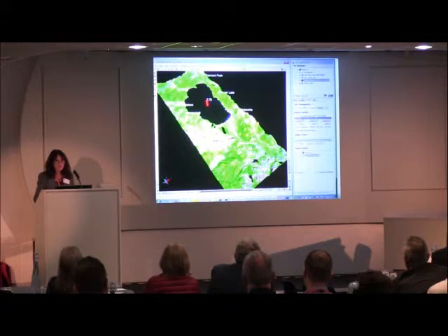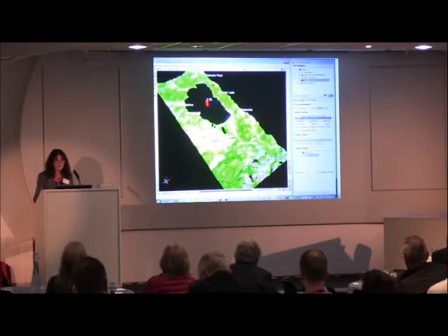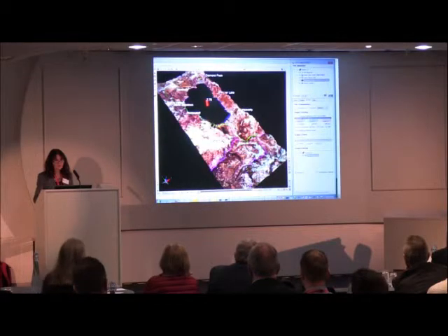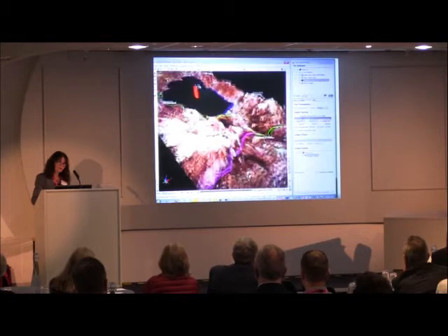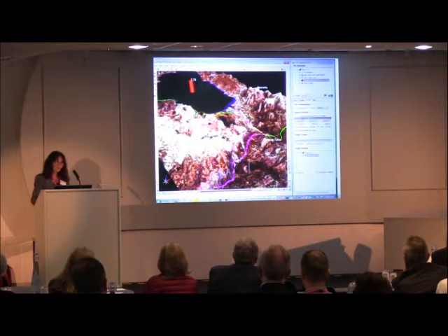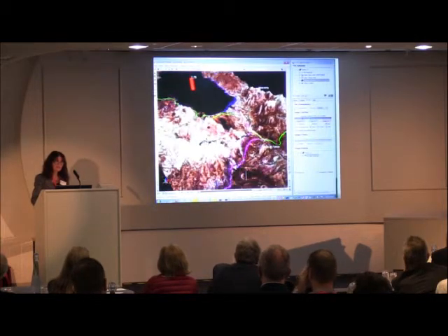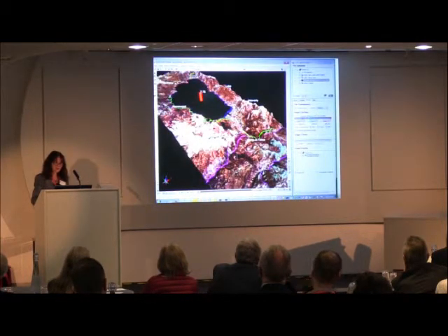On the render tab here, at the moment, we're looking at layer 2, 4, and 6. If we adjust the color bars, if I move the green, you'll see the color changing. What you're seeing now is the white, or the light blue, represents snow, and the dark blue represents the lake levels. I'm just going to show the 4D side, because one of the key things with this particular data set is looking at changes in the lake level over time, which is what you're able to see.